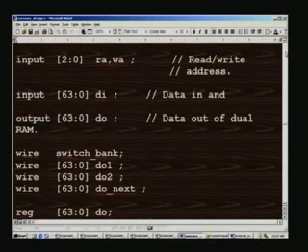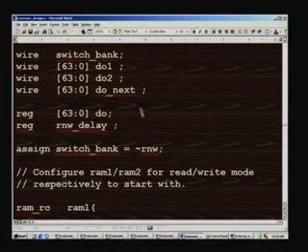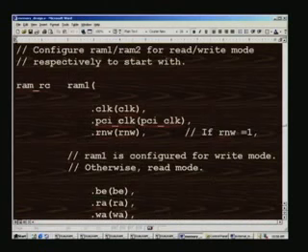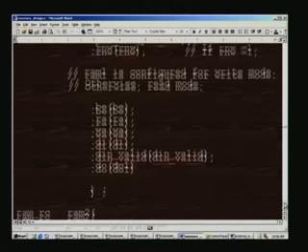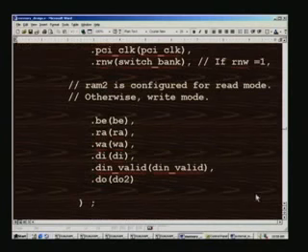as you could have seen here, DO1, DO2, and so I mentioned in one of the test benches way back how we call lower submodules from the top design, and this is the first thing I think we have encountered, calling the submodule, and this is a separate file which we will be looking into shortly. So we see that if R and W equal to 1, RAM 2 is configured for read mode, otherwise write mode. It is exactly the reverse of the RAM 1 condition.